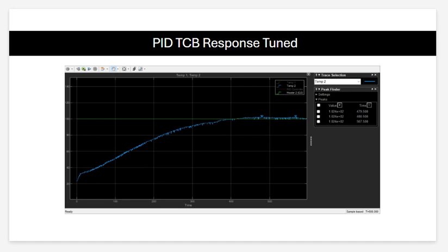And to summarize all this, the open loop response helped identify the system's natural behavior, and we calculated the slope to estimate the transfer function parameters. Using those values, we computed the initial PID gains, and the untuned PID shows overshoot and oscillation. After tuning the system, it became a lot more stable and a lot smoother, and overall the tuning process resulted in a well-controlled, stable system.